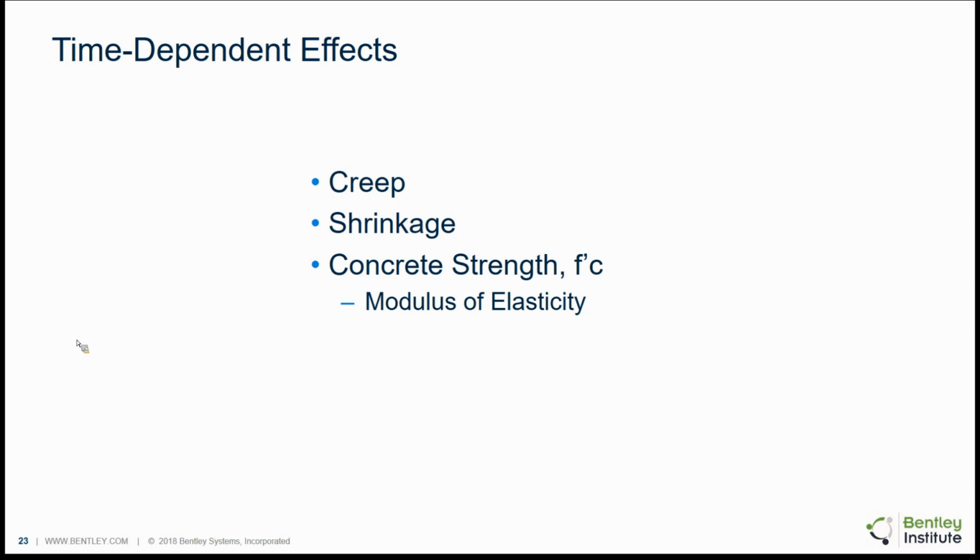I want to move on now to another topic, that of the time-dependent effects. Because these effects that we've talked about, the axial shortening, that's the elastic shortening, that's an immediate shortening. It's not a time-dependent effect. But I want to talk now about the time-dependent effects, in particular creep, shrinkage, and concrete strength, which impacts the modulus of elasticity.